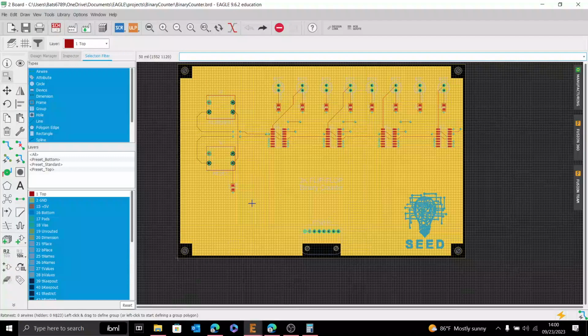So I don't have to manually wire up all the VCCs and all the grounds. Everything is just there. There's other benefits to this too. For example, during manufacturing, I made sure the ground plane was directly below the circuit. Why did I do that? When you start dealing with advanced signal processing stuff, one thing you start to worry about is airwaves interfering with your circuit. And a good design rule is to put a ground plane below all your sensitive circuit electronics so it can help absorb that magnetic flux. So it effectively acts as a giant grounding antenna without actually turning your traces into antennas.